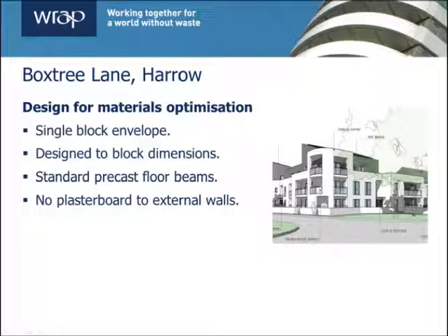Materials optimization was achieved firstly and most effectively by choosing a single block for the external walls of the building, in place of commonly used cavity wall construction methods. This simplifies the design considerably, as it eliminates the separate construction of the internal skin, the introduction of separate insulation material, the need for wall ties, cavity trays, and associated detailing such as weep holes in the external skin.